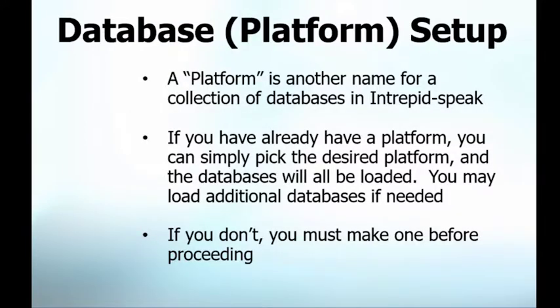And then to the database setup. So in VehicleSpy, we have what we call platforms. And a platform is basically just our terminology for a collection of databases. So you load multiple DBCs, multiple ODX, A2Ls. We save all of this under a platform name. So it's up to you to define that platform name, but this is where everything gets stored. So if you already have a platform created, go ahead and add databases to it. Otherwise, you create a new platform, you give it a name, and then that's what VehicleSpy will reference the rest of your setup.